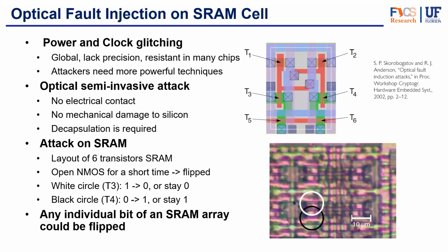And in this example you can see that the SRAM has been divided into 8 distinct areas, and they have shown that with these optical beams we could inject a fault in this area, flipping the 1 to 0, or staying at 0. Here we could inject based on the intensity of the laser light, at the same time as the location of the PMOS and NMOS transistors.